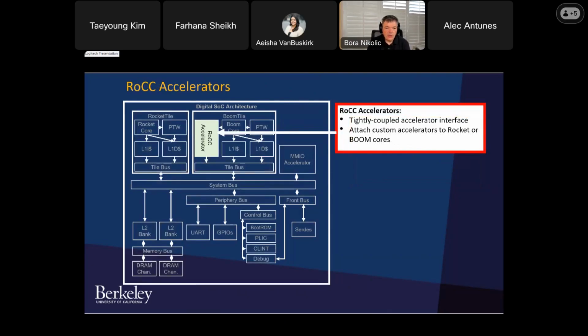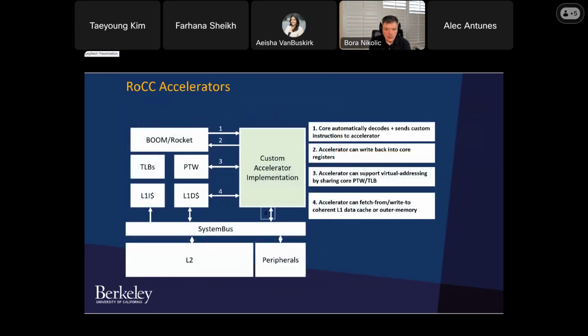Walking through the rest of what gets generated in Chipyard, there are so-called tightly coupled accelerators that conform to the RoCC protocol. It's a very simple protocol where the processor core decodes an instruction, and if it corresponds to the specification for the RISC-V coprocessor, it will send it to a coprocessor. The coprocessor and accelerator will execute that instruction with the data that the core has fetched, and signal back to the core that it is done. It is a relatively simple protocol that is out there.